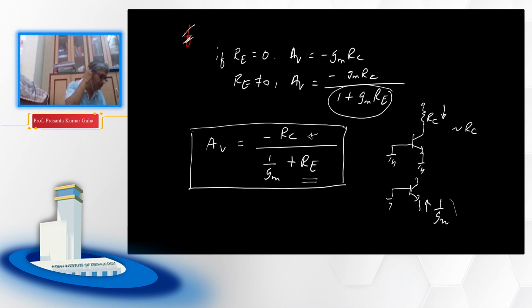But the important point is your gain is going to fall if you add your RE. We will discuss in the next class that incorporating RE will improve your input impedance or input resistance. So that is one advantage of including RE.